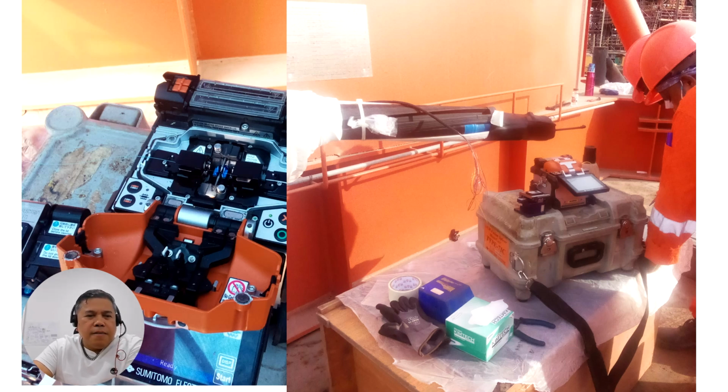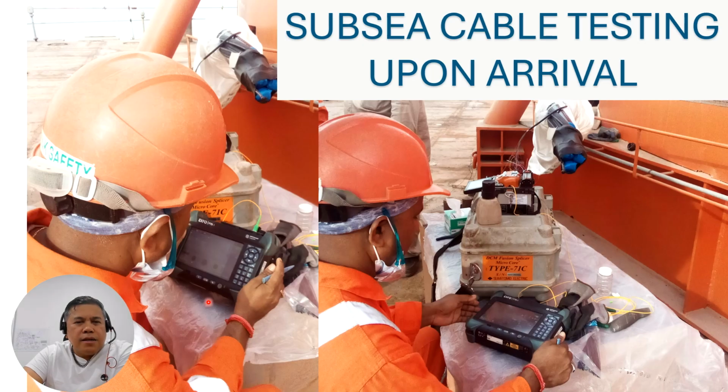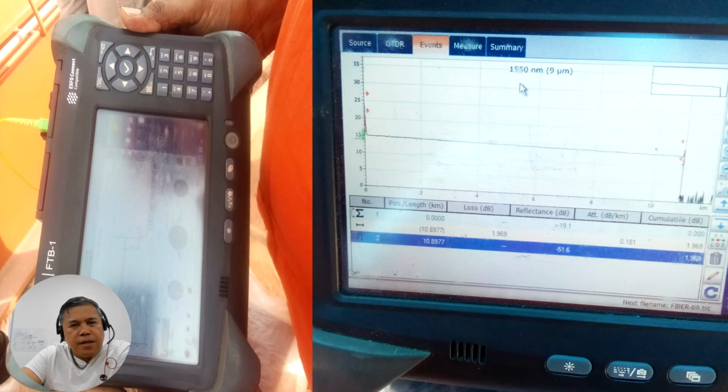You can see here. Then this is the technician. This is a fiber optic technician, and this is the result. You can see the result. You can see 1550. The testing, by the way, guys, we have 1310 and then 1550. You can see any reflectance, losses, etc. And then when you check this, there is a pass, and you can see any failure, any losses during the testing. So that's the way how we do the testing.